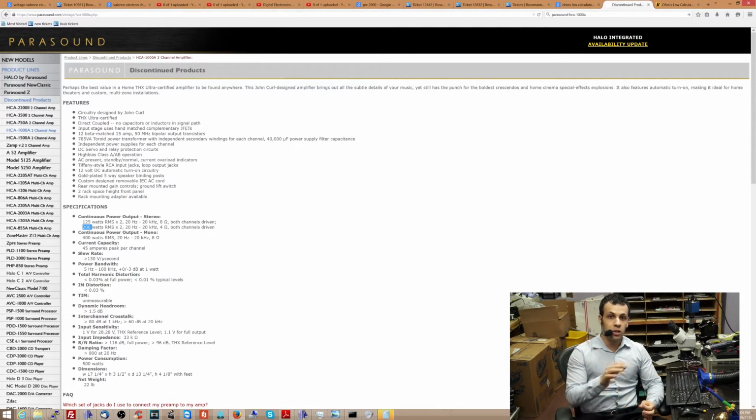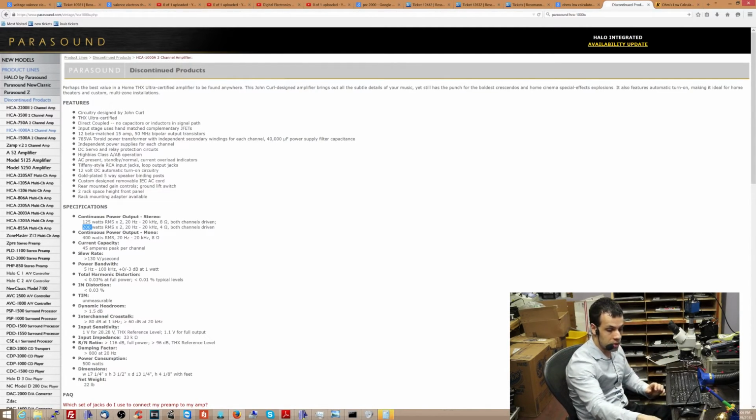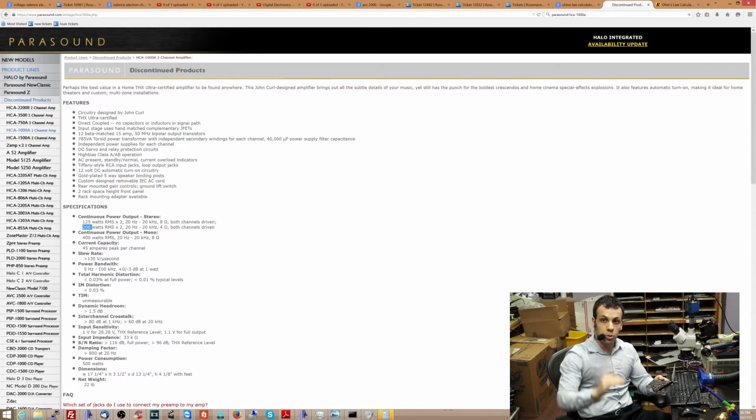So keep in mind that you cannot set current. What you set is the complexity of the circuit and the voltage, and that's how you get power. Depending on what the circuit is doing, its impedance, resistance, however you want to phrase it, may drop or may go up, and that's going to set the power usage. But at any given voltage, the current that's going through it is not something that you can set. You set that by changing the resistance of the circuit. You can change the voltage of the circuit, and you can change what's in the circuit, but you can't say, "I want more amperage to go through the circuit." The only way to send more amperage through the circuit is to up the voltage or lower the resistance. And that's how voltage and current work. That's the difference between them, and hopefully this makes some sense to you.